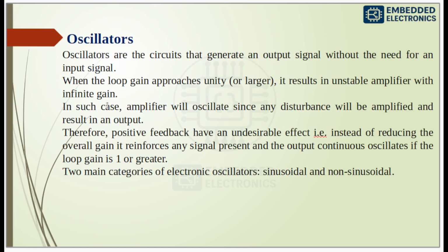So positive feedback has an undesirable effect, meaning instead of reducing the overall gain, it reinforces any signal present, and the output continuously oscillates if the loop gain is 1 or greater.